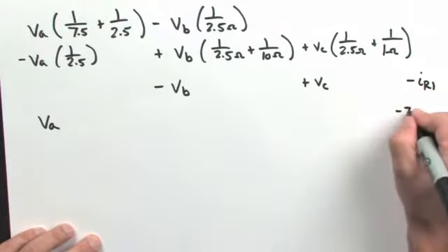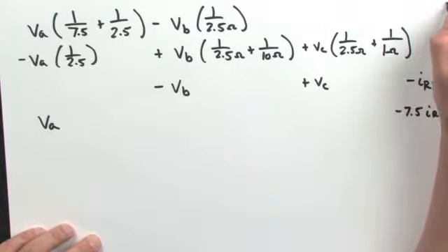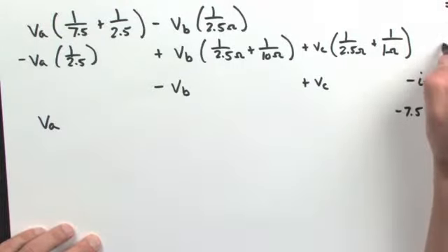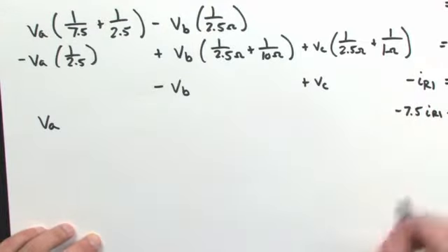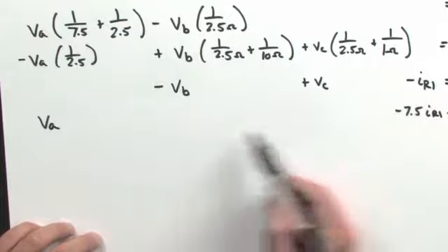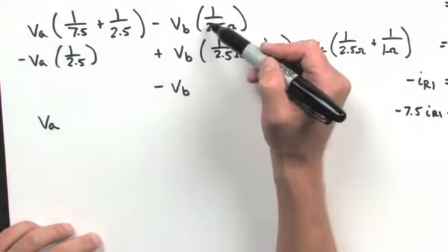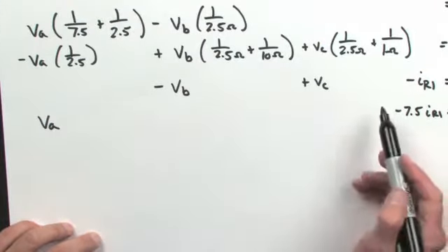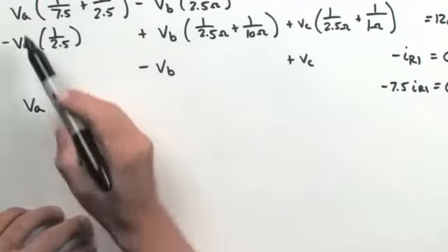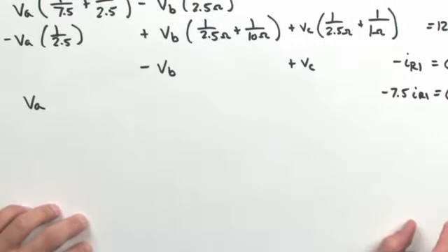R1. This equals 4.8. This is equal to 12 amps. And both of these are equal to 0. Okay. So writing it out in this form, all of the equations that we developed, the node equation, the supernode equation, and the two constraint equations, we clearly see that this is a system of equations in 4 unknowns: VA, VB, VC, and the current through resistor 1.